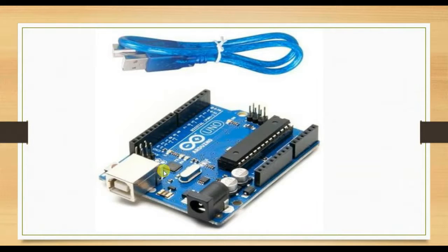This you can see over here. This TQFP packaging chip is a controller. There is an Atmega controller which is used as a programmer to program this main IC, the Atmega 328P that was used in Arduino Uno. So using this USB cable, we can directly program this main IC. Okay.